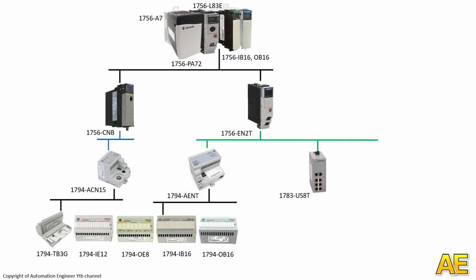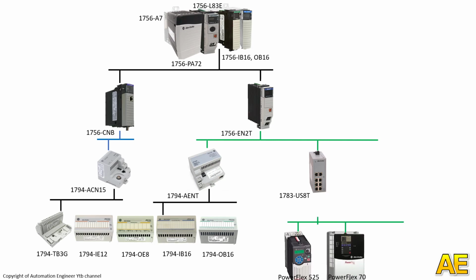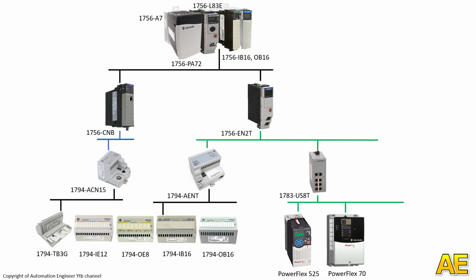Then we connect the inverters, for example PowerFlex 525 and 70. Also other Ethernet devices, for example the weight scale transmitter. That's done for the I/O and Ethernet devices.